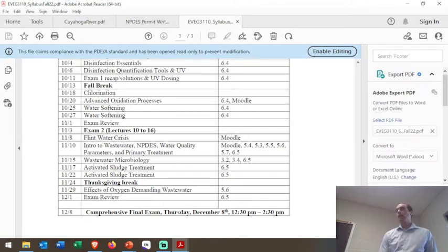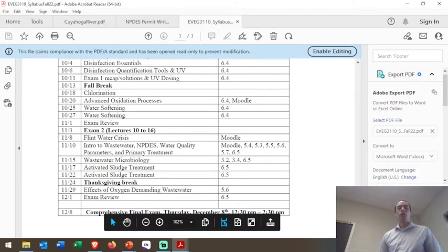In fact, a lot of times what's really convenient is to simply use microbiology. So we feed the organisms, or really the waste itself is the food, and we give them a chance to take in as much oxygen as they can and want. That's the activated sludge stuff we'll talk about.